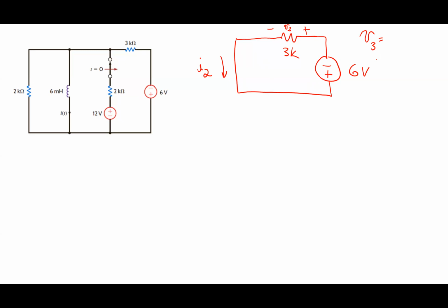How's that equal in terms of the currents and the resistances that I have there? How would I write V3? In terms of the way I2 is drawn, how would I do that? V3, so V3 equals I2 times something, right? How would I set this up? 3,000. Was it? 3,000 times I2, not negative?